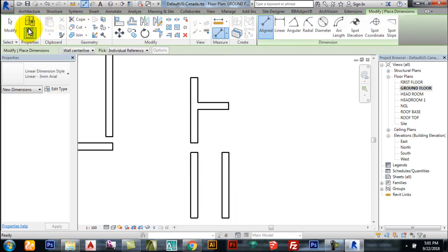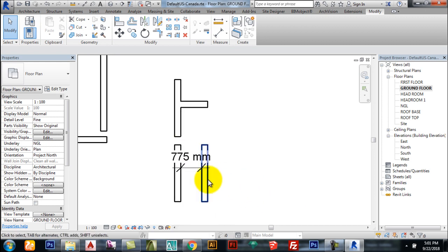So if we check what we have here, it should be wall faces. We're using this to have 775 here instead of 1000. Instead of just moving it, just note that whatever you are offsetting, always add your 225 wall to it.